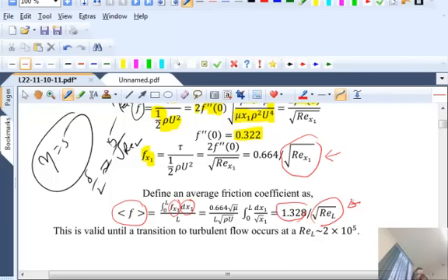You said the first one is for the local friction, and the second one is for the total friction up to that point. So even for the first one, x equals L, that's still local. Right. So the factor that determines it is whether you are using 0.664 or 1.328. The length remains the same. Suppose I have a plate and I measure up to 10 centimeters.